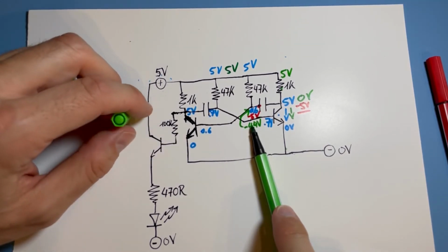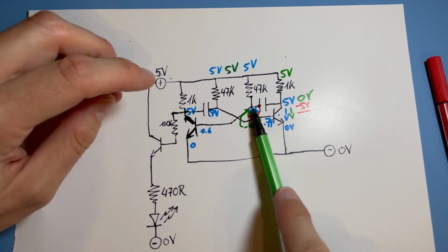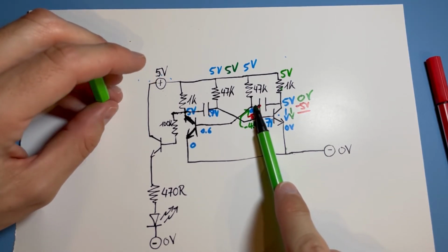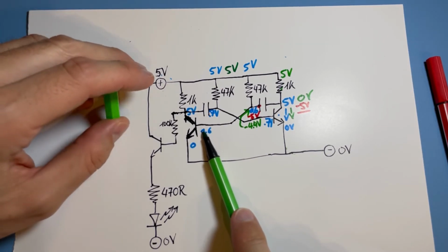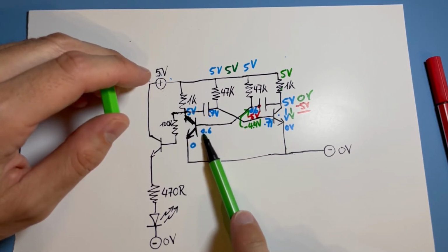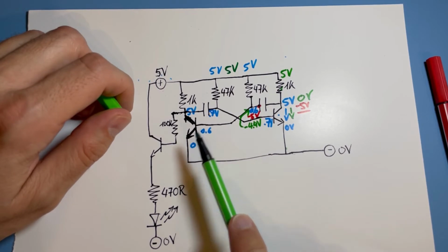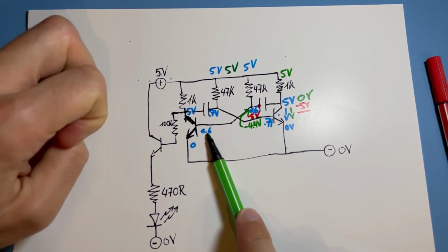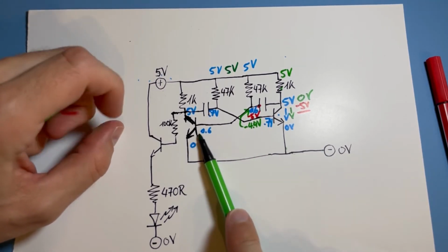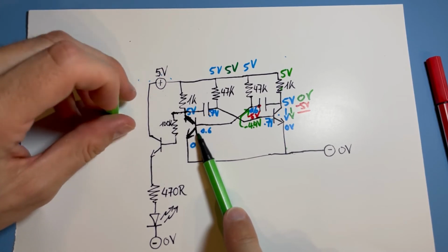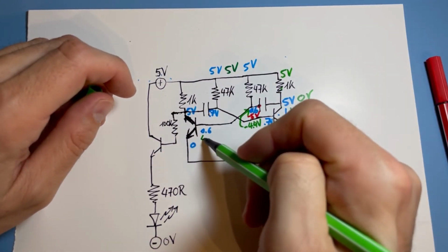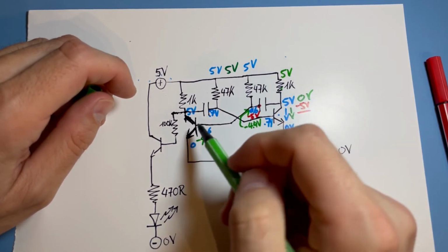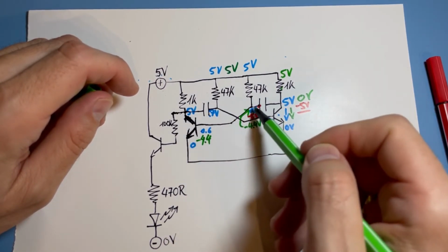And because it's at minus 4.4 volt, at this point here at left of the capacitor, this base is not higher, because it must be 0.7 higher than the 0, so it must be 0.7. And it is at minus 4.4, and this base is never conducting now. It cannot be conducting. So here we also have now minus 4.4 because there's the same potential at every place here.